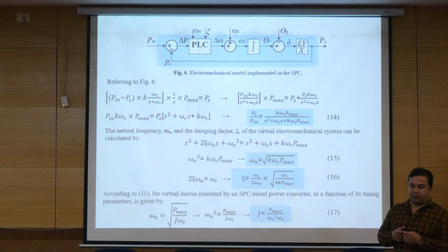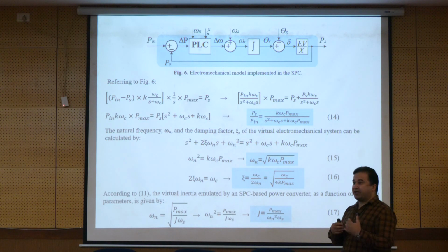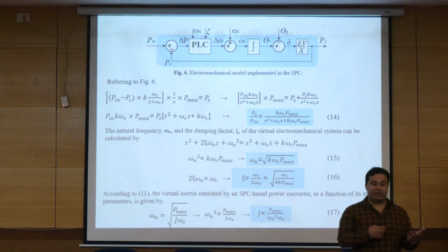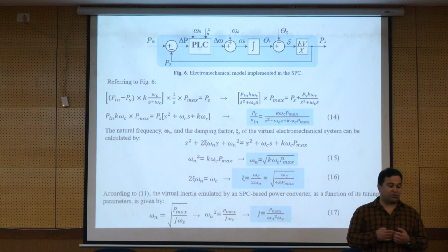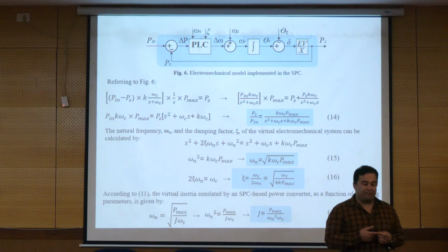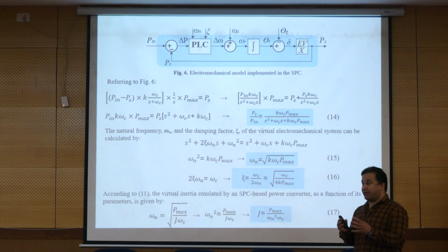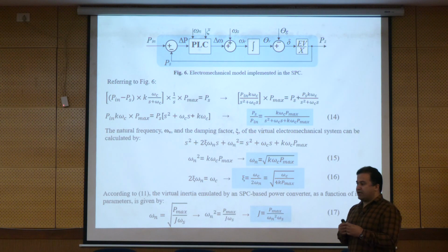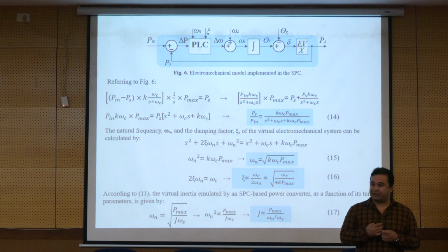In ABB, they have a model that considers, for example, the reference voltage after the filter or before the filter. They call it the power synchronization controller, PSC. In the first version, it could not work for the weak grid, because most of them worked in a stable grid.